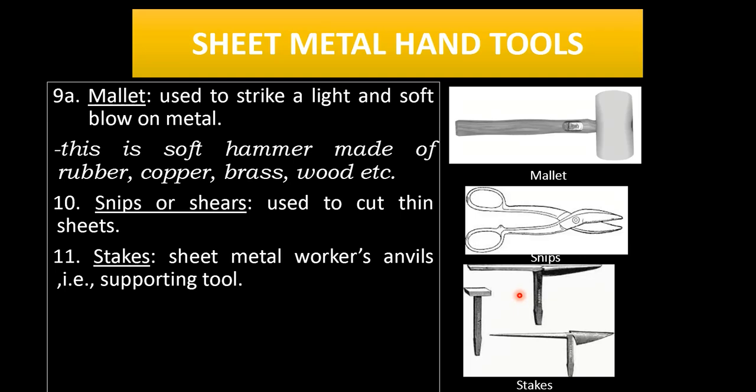Generally an anvil is very heavy, but these are a little lighter in weight because of the design you can see over here. The different shapes help us perform different operations. Like, we have this funnel-like shape. We can keep the sheet metal on top of it. Sheet metal is flat generally, and we can start hammering it from the top. Once we continuously hammer from the top, the sheet metal will acquire the shape of this funnel.